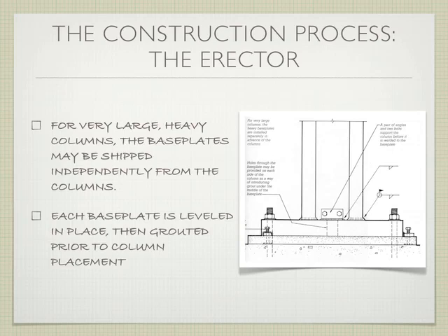It would depend on what the engineer designed in terms of tying that in, because obviously you need to tie the steel column into the foundation and into the rebar of the foundation. So depending on how the engineer designed it, those bolts should be tied into the rest of the rebar system. And so it could come to a plate that's then welded to the rebar. It could somehow be tied in differently, but that's more of an engineering question. Beyond my realm, most of my construction experience is at the residential scale, not at this scale. So I don't have personal experience for what that looks like in the foundation.